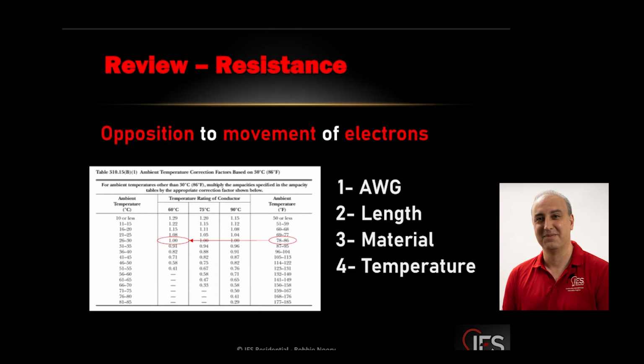But what happens if the ambient temperature is higher? Let's say in Phoenix, Arizona, we have a city that tells you, hey, we consider attic ambient temperature in Phoenix to be 96 to 104 degrees on average per year. So you can't use the numbers that are in 310.16 anymore. You have to take that number and multiply it for Romex by 0.82.